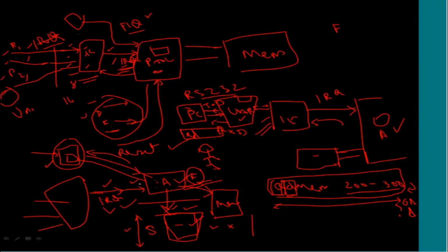Okay, this is a typical example in a real life scenario where you may have to split your handling of interrupt in two different functions, and then perform the first job, copying the character from the interrupt handling peripheral and then copying it to the memory. Then, when the complete command is received, call this function to run the command. So this will be the second level of processing of serial port interrupt.